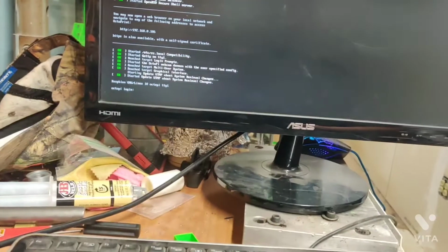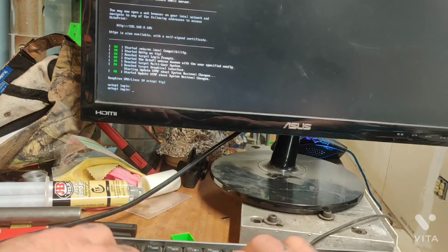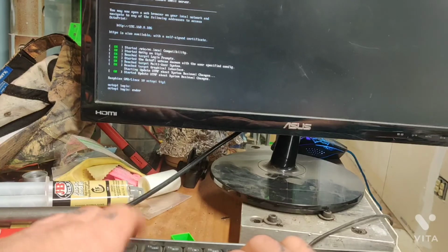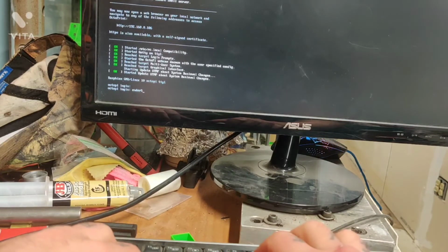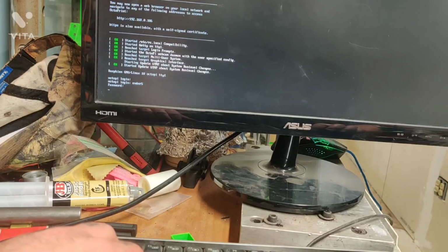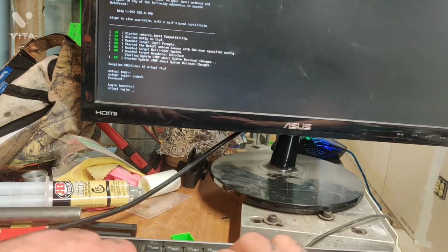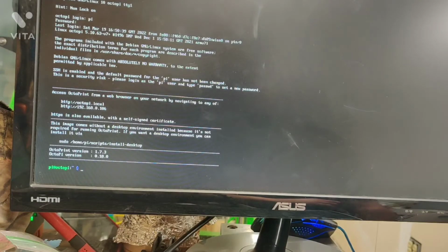Now we should be able to come over to our Pi, and it'll ask for the login page for our OctoPi, and we named our OctoPi Ender 5. Type in the password that we set. Login incorrect. Of course it is. Alright, so it doesn't actually want your OctoPi login. It wants your Raspberry Pi login. And the default name is Pi, default password is Raspberry.